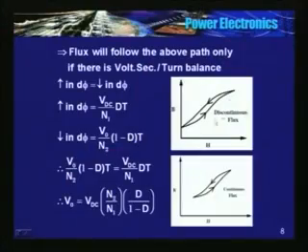What is the transfer function now? We have not derived the transfer function for the flyback converter. What is the input output relationship? I had shown these two flux plots, or variation of flux in the core. It starts from 0 and comes back to 0, the same point. Here also it starts with a finite value and comes back to the same finite value. In other words, there is a steady state. It can happen only if there is a volt-second per turn balance.